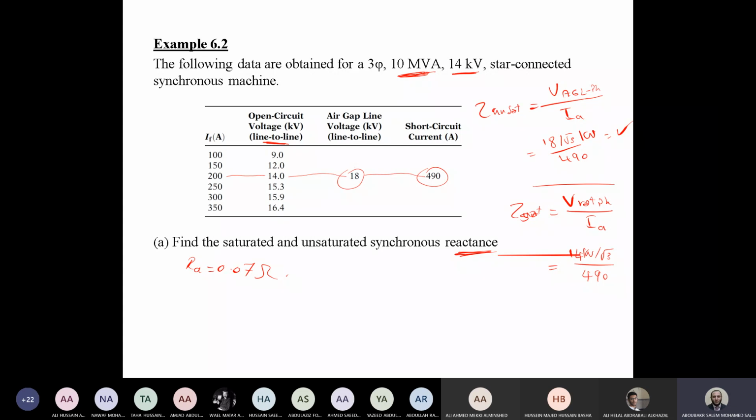The value that we should select on this breaker should be the same as the rated current of the load, which is, for instance here, if it is 20 amps, so you should select the switch from 20 to 25, like that. What will happen if a short circuit happens on this heater?